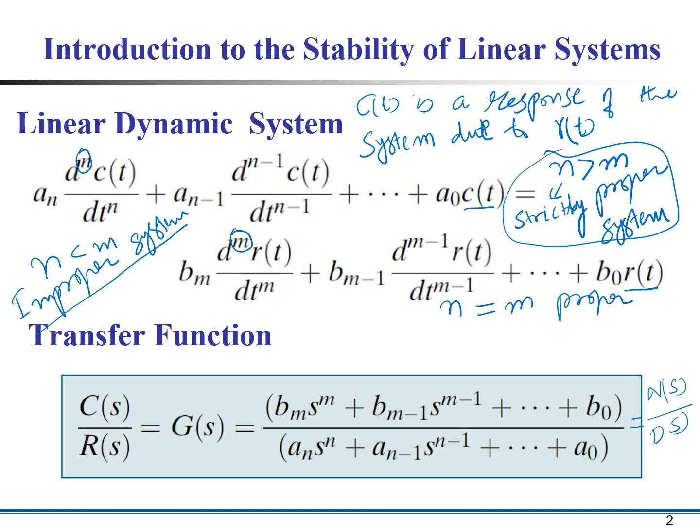So a transfer function always consists of a numerator polynomial and a denominator polynomial, as it is the ratio of the Laplace transform of the output and the Laplace transform of the reference input. But if we look at the transfer function, it depends upon the parameters of the system, and the transfer function of the system does not depend upon the input and output of the system. The stability of the system depends upon the denominator polynomial, and we sometimes call this polynomial the characteristic polynomial.